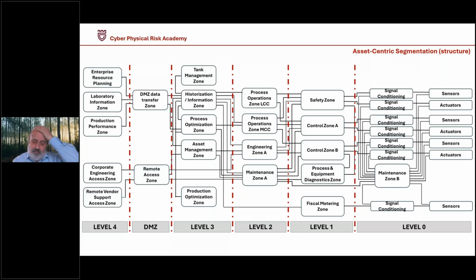And then level 2, that's the supervisory layer where we have the operator stations. I split it up here basically. We have 2 control zones. So we might have operators overseeing all the zones, and we might have an operator station, a local control center station, that only looks at a small part of the process, in a smaller area.